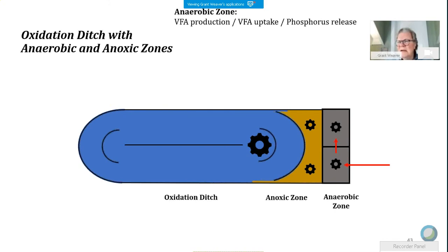I just switch them every day. If that isn't enough, then I'd be turning them both off for increasing lengths of time. You only need to resuspend them enough so that all of your return sludge doesn't settle out in that zone, or so that it doesn't get so septic that it starts to digest the sludge and you're releasing too much phosphorus.